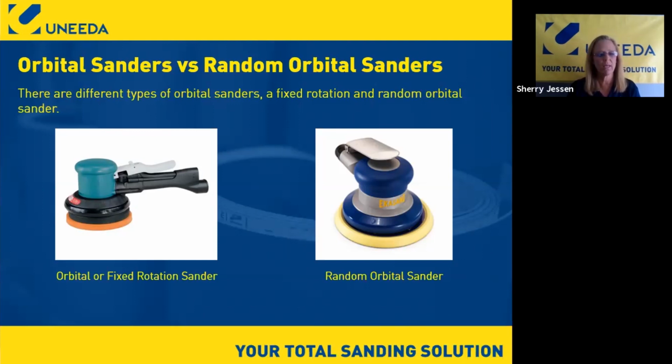When we need to really get aggressive, if the seam is really raised or there's a lot of glue in between, sometimes it's just a little bit hard to do with the random orbital sander, especially a 3/32, which we'll get into a little bit later. But a fixed rotation sander tends to be a little bit more aggressive, and you get more of a swirl pattern out of it, which is one of the reasons we don't see it in the wood industry as much. The most widely used sander right now in the wood industry, I would say, is the random orbital. There are different sizes, but predominantly the 5-inch.